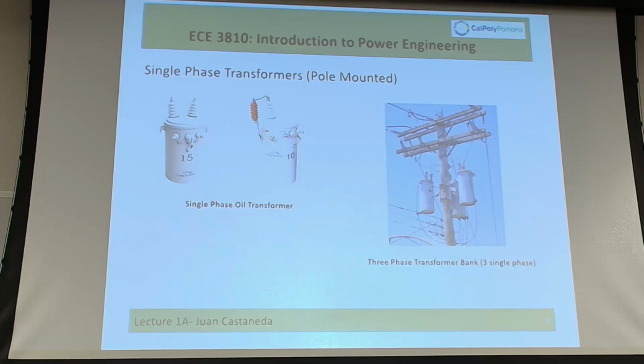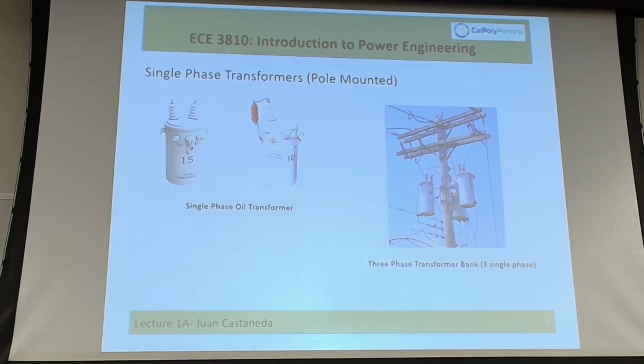The ester fluid, different from the organic oil that we have been using for the last, I don't know, 100 or so years, has a much higher boiling point. So you can heat up the oil to a very, very high temperature, and you're not going to have a flash internally, like ignition.